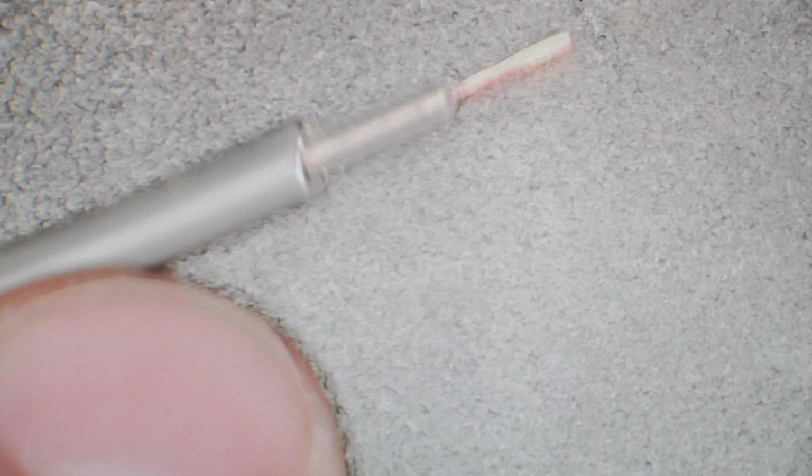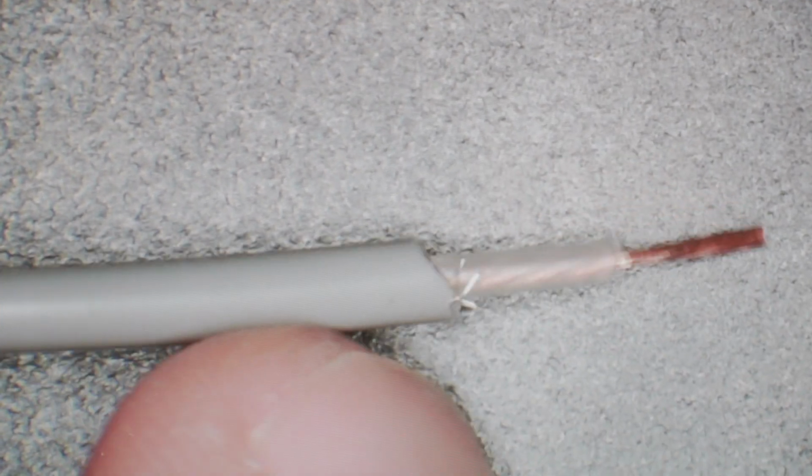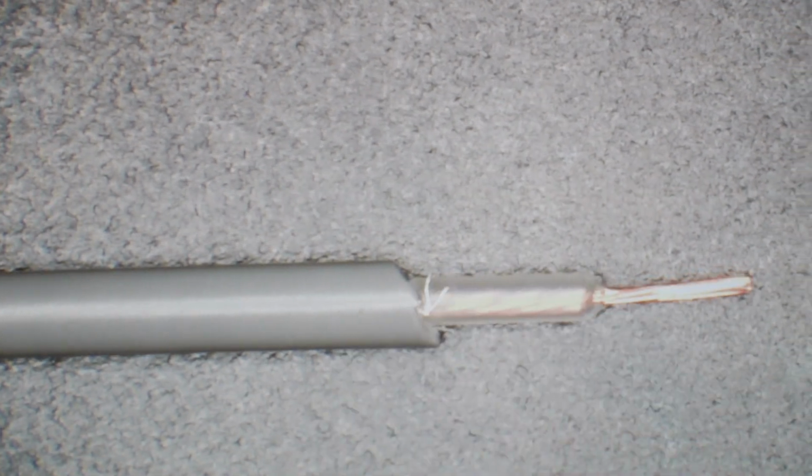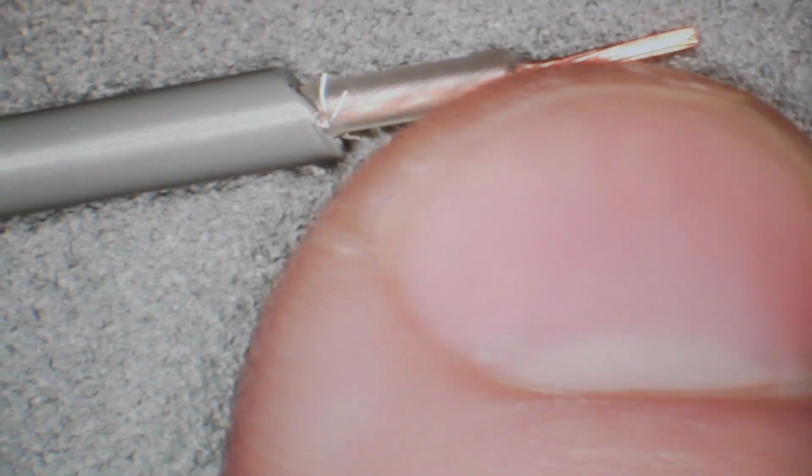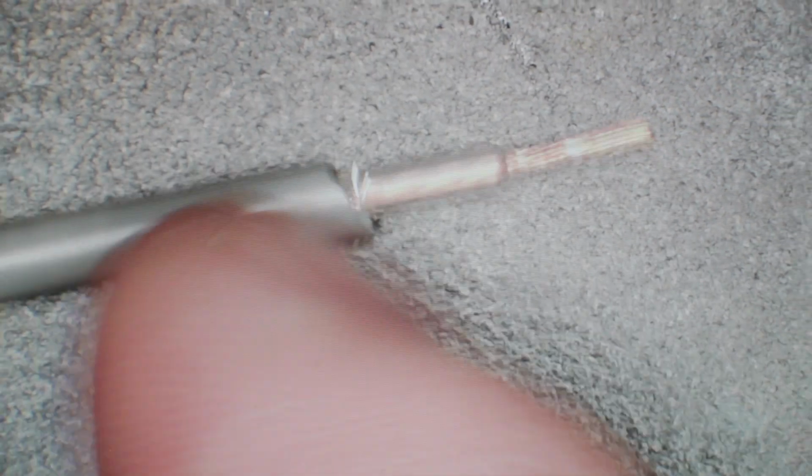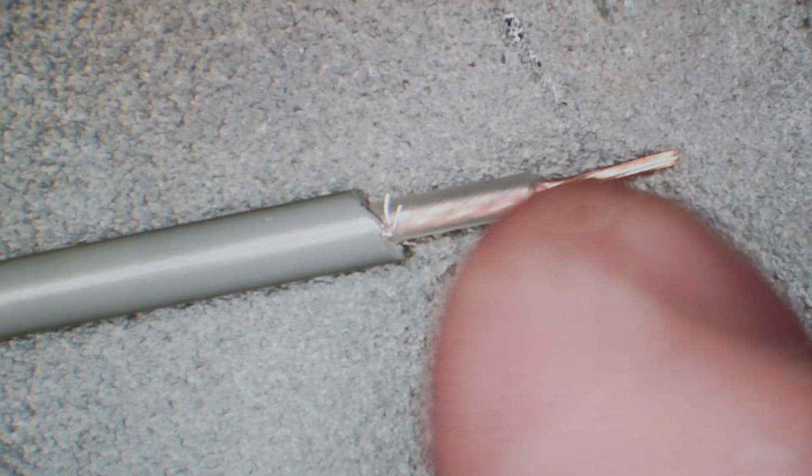And this is a cable that's already been pre-done. We've cut it back. We've ensured that no antenna portion is up anywhere near the signal, because that will cause noise or interference. That's what happened in the first part of our project. This shielding was not trimmed back like it is here, and we had some signal problems. So this step's super important.